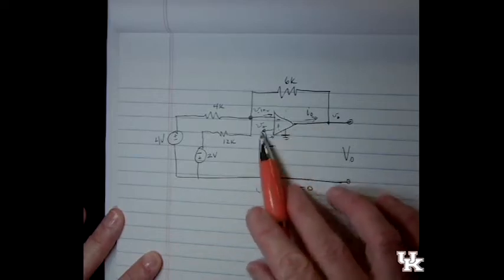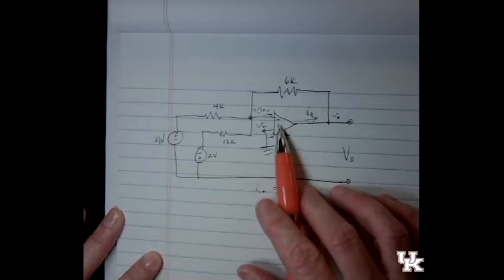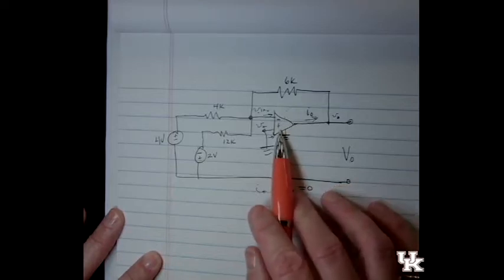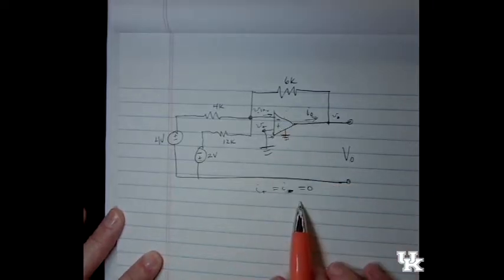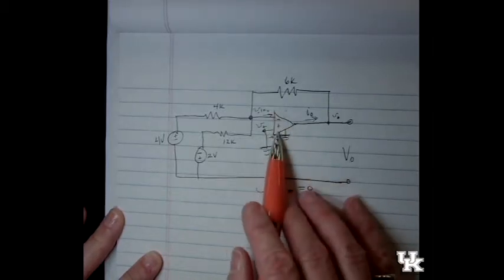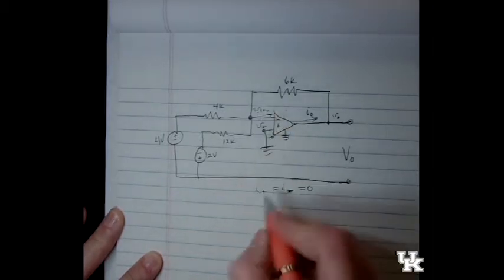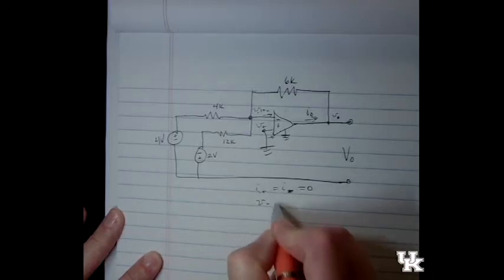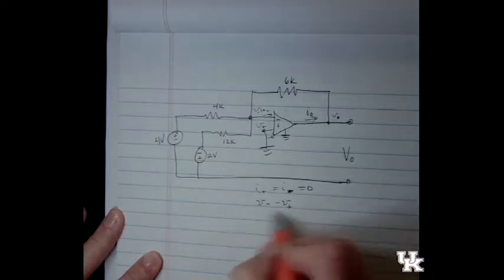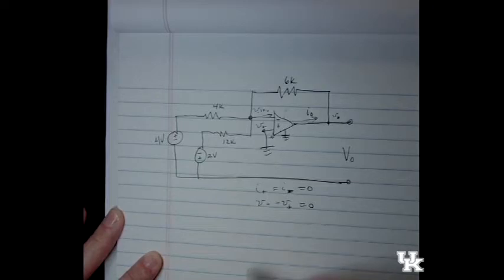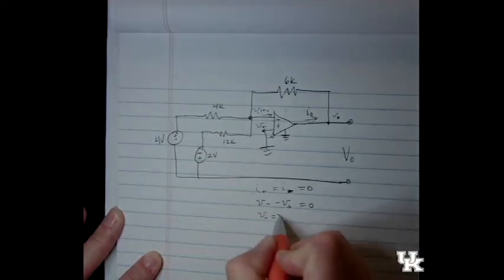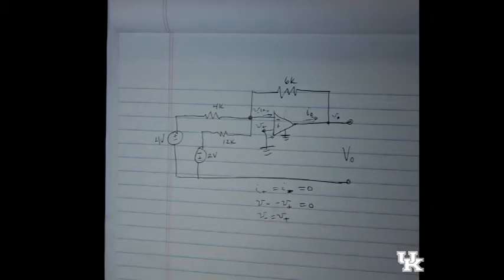So on the input side, we've assumed that there's a very high resistance here at the input, which prevents any current from flowing in. And because there's no current between these 2 nodes, we assume that they have no voltage difference. If we were to subtract one from the other, we would get 0. So we can either say the difference is 0 or the 2 inputs are equal to each other. So if we can figure out one of them, we automatically know the other one. Right?